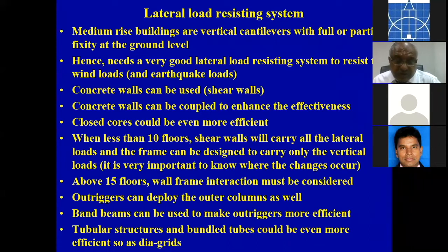So this is called risk assessment. For every element, when you are designing, you will not only look at the bending moment. You will look at whether this bending moment changes over the lifespan of the building. If the bending moment can change, then you have to include that change in your design. For example, when you design the building, you will model the building, the foundation, then car park levels, then the transfer plate, and then the building above the transfer plate.